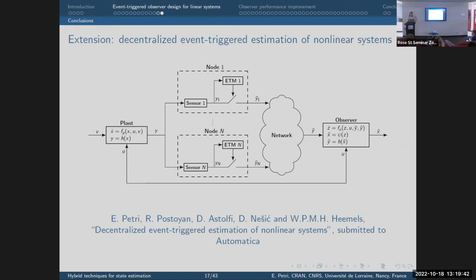We need the difference between the last transmitted output and the current output to be enough to trigger a transmission. So we have to increase that epsilon, which implies that the ultimate bound of the convergence will be bigger. But in any case, when there is noise, it cannot converge perfectly to 0, there is always a bound. So you just need to know the bound on the noise.